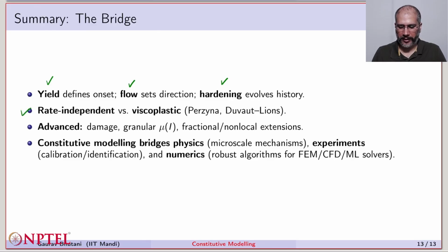There are rate independent models versus rate dependent or viscoplastic models. There are advanced models available as well that take care of damage and confining pressure rheologies. The constitutive modeling in general requires a lot of microstructural study.